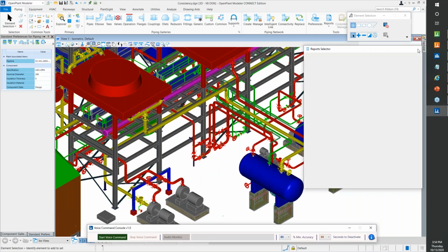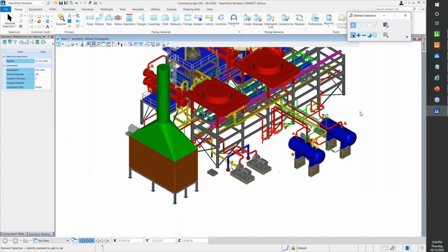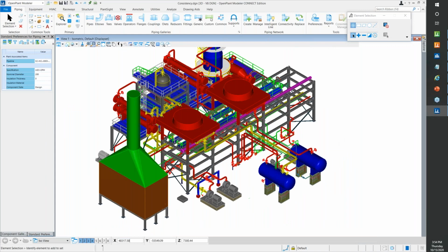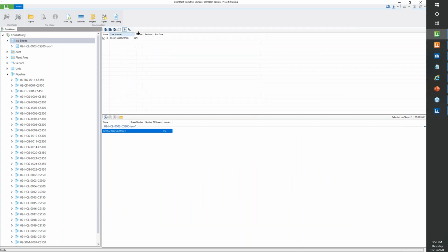Now as a part of the modeling, where we want to extract the deliverable like isometrics. Yes, isometric manager, which will allow you to generate the isometrics here. This is the line number where we have to generate it. Once you have created the model, you can process it. You can see here the time frame which is showing to generate the isometric drawings over here.